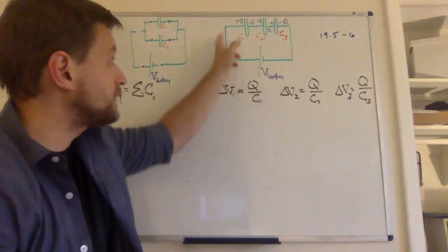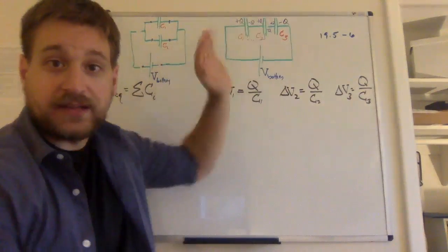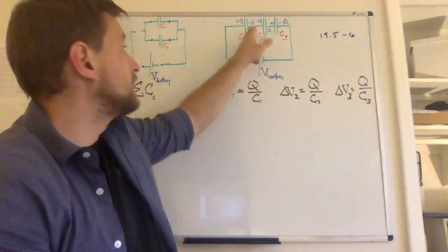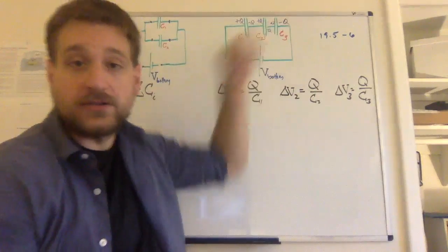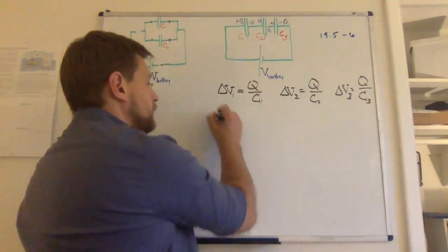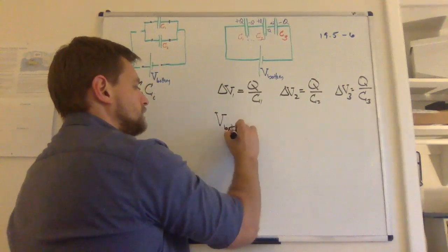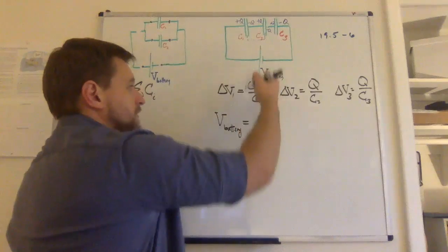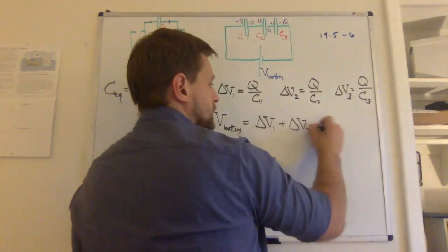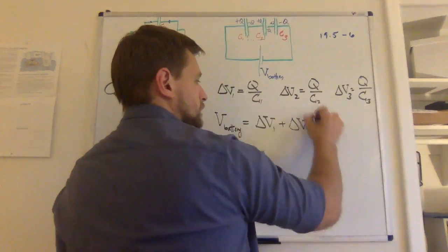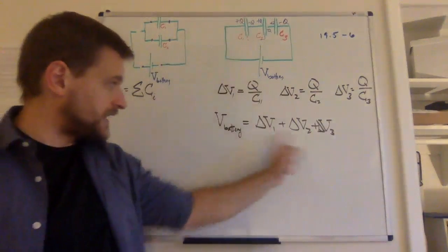Imagine we're walking this circuit, like we go from a plus Q, hop over the gap to a minus Q. That's a decrease in electric potential. And then we do that again, there's another decrease in electric potential. And we do that again, there's another decrease in electric potential. So the combination, capital V, of the battery has to be equal, in magnitude, to the potential differences across the 3 capacitors. Because we go up this much, we got to go down that much.